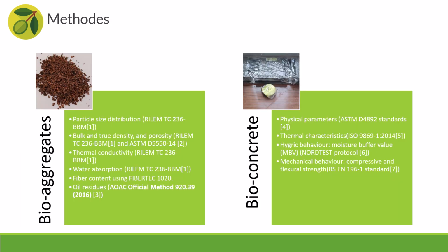The methods adopted here were guided by international standards. For the intrinsic characterization of olive husk, as we already stated, we followed the Rilem TC 236 BBM recommendation, which is specifically tailored for bio-based building materials. In terms of bioconcrete testing, we followed different standards, from British to international standards, covering bulk density, porosity, thermal parameters, and mechanical properties.